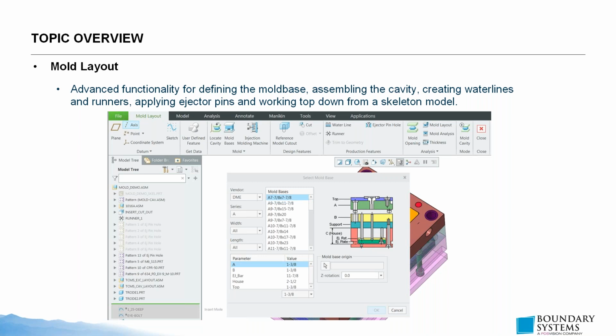for reference control and management of the overall mold design assembly, especially when you get into mechanics and externals on the mold base itself, such as moving hydraulic cores and unscrewing assemblies. That adds a notable layer of complexity, and in virtually 100% of cases we have an overlap of positional and mechanical definition that intersects both the mold base as well as the cavity insert assembly. So having those things at that level and managing them with the skeleton model becomes highly advantageous.